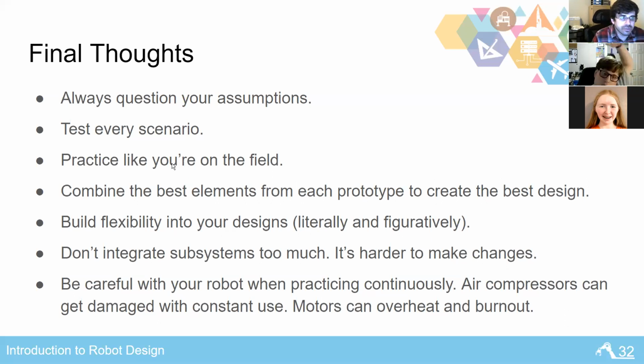So what I want you to take away from that is hard game pieces, compliance in the robot; softer game pieces, compliance just in the game piece. And you can either have compliant mechanisms or have rigid mechanisms in that case.